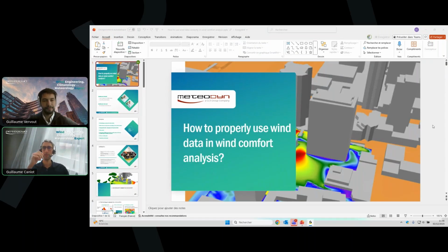Another question is about local methodology, some of which recommend taking altitude or height at 100 meters or 150 meters above the ground. With our product Urban, you define what is called href at 150 meters, and you integrate weather data at this reference surface.